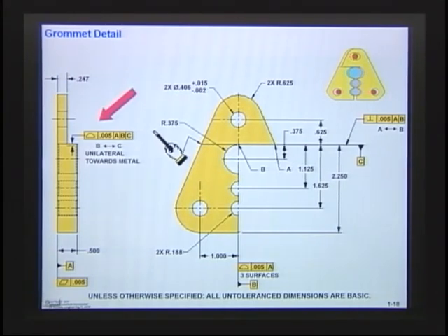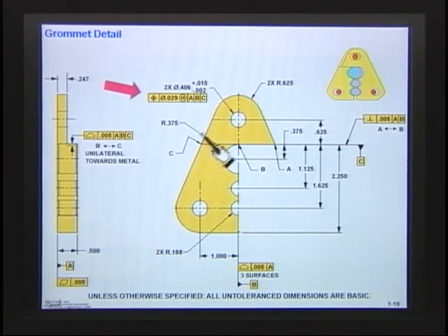All right, I'm going to go in after the most important things first, so let's take a look at what I'm doing next. The next thing is I came in and I located these holes. Now, there were 2 holes on this part, and they matched up to the bulkhead. Remember, there were 3 holes on the bulkhead, and it happens to be the same size hole. Now, how did I calculate that 29 in there, that 29 position? That was done with the floating fastener.